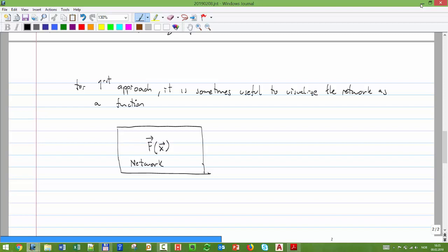And here I need one input, which is system characteristics. These are things like, for example, the C and the N of the wells. You need the CT, you need the S of the tubing, you need the S of the flow line, you need all of these data, and on top of that you need reservoir pressure.